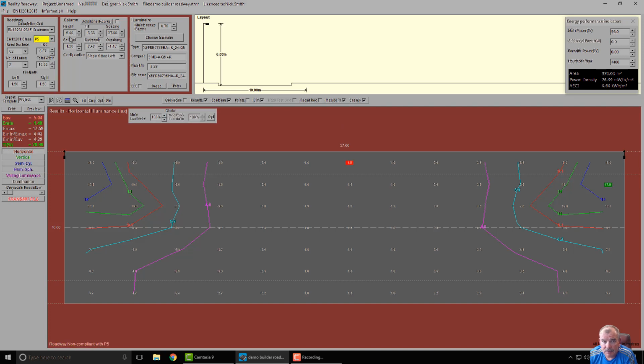We can then go through and dim that and select P5, and then by using this opt facility button here, this will dim the lantern down and the additional luminaire if you've set that up in the additional row, and that will dim it down to a level that will give you a solution that works for that particular geometry. So what it was saying here is that if we dim the main luminaire down to 60% of output, that will give us a compliant solution to P5, and we can go away having saved 40% energy on the installation.